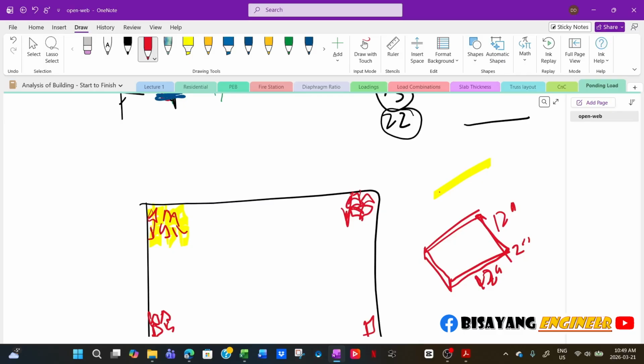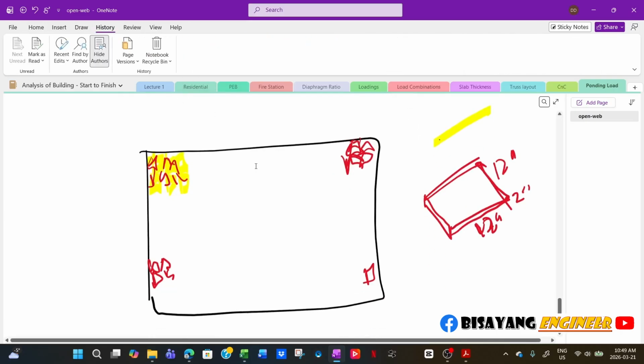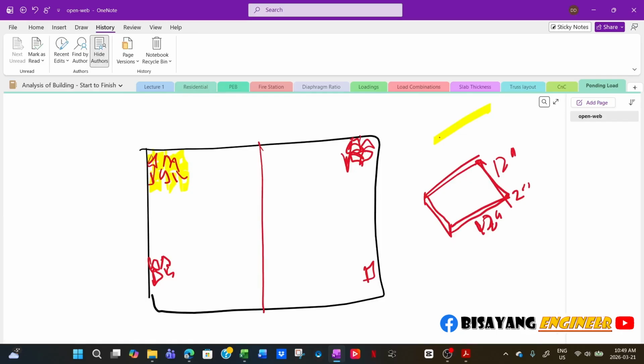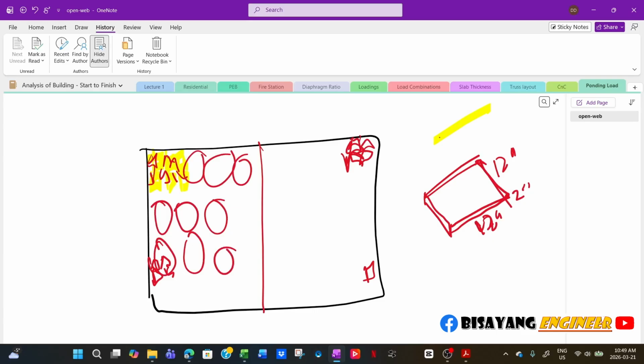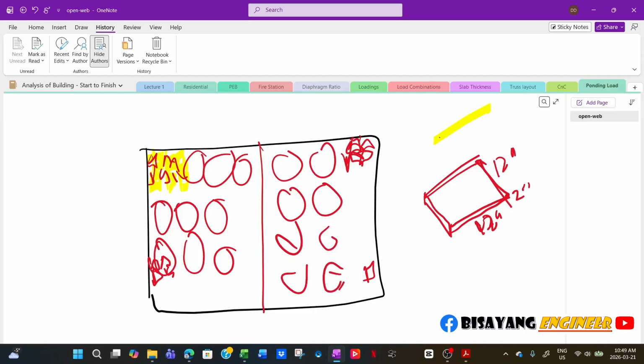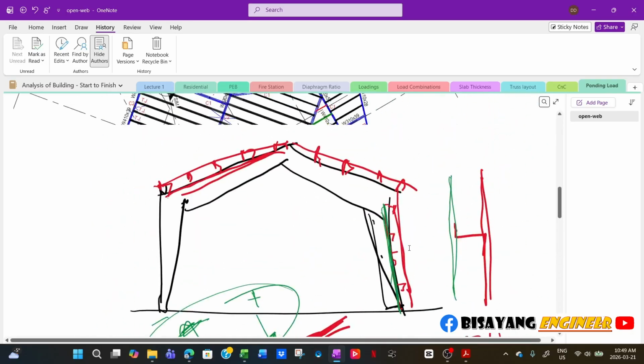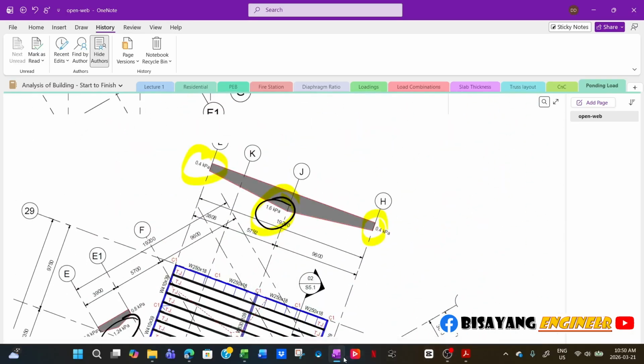In our case, every time there is a typhoon, we will put them. So this is a common roof type. When there's a typhoon coming, in the province we will put a counterweight on it. But here, we sometimes use bags of sand or used tires. So that is to counter the uplift on the roof. That's basically the explanation for that.